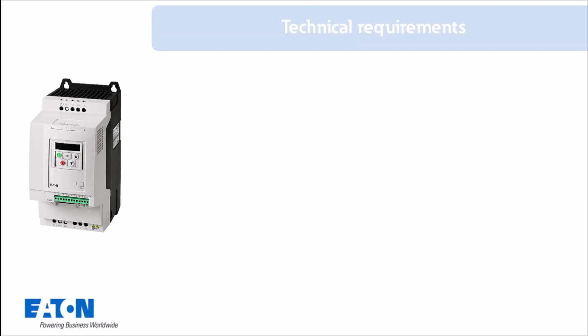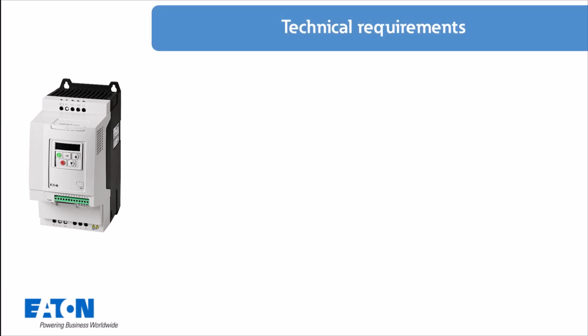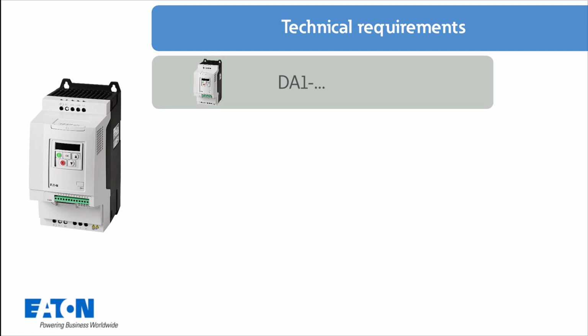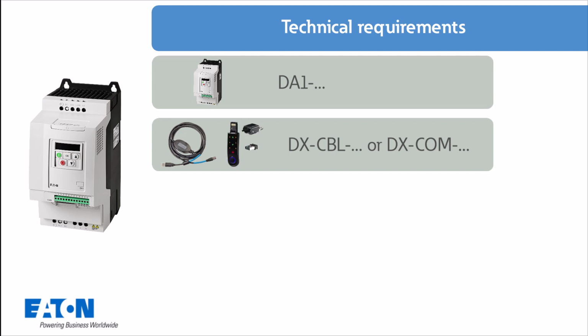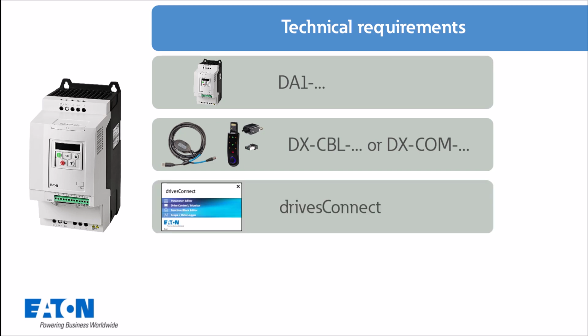The following technical requirements must be met: a DA1 frequency inverter, a serial communication cable DX-CBL-PC3M0 or a Bluetooth communication stick DX-COM-Stick3, and the programming software drivesConnect.